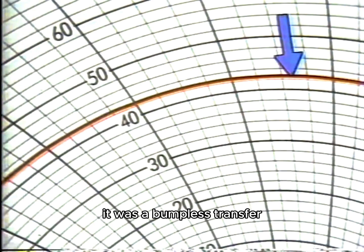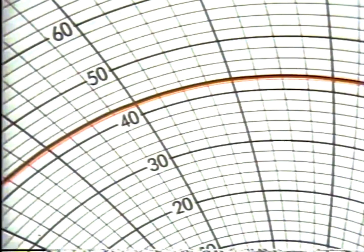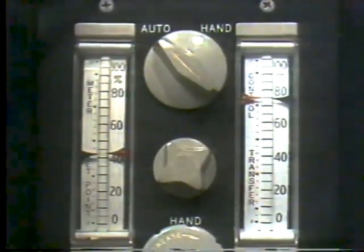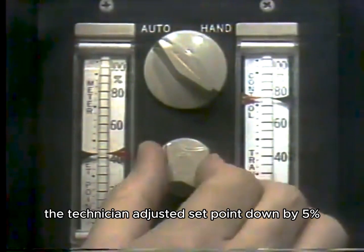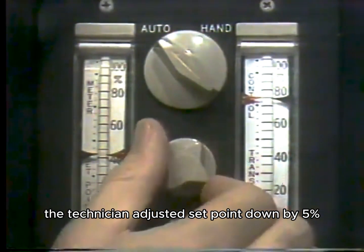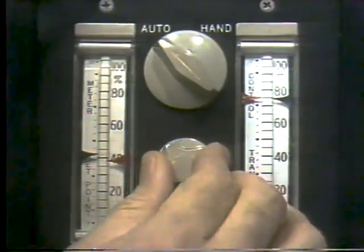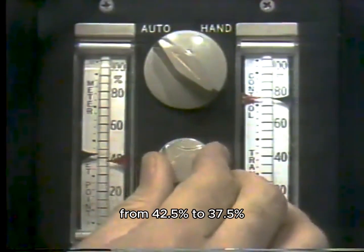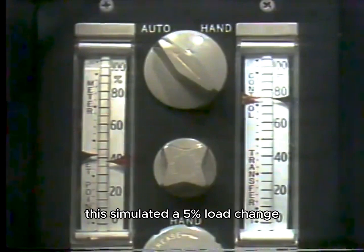Since the line did not move away from set point, it was a bumpless transfer and the system remained stable. Once the system was in automatic and was stable, the technician adjusted set point down by 5%, from 42.5% to 37.5%. This simulated a 5% load change.